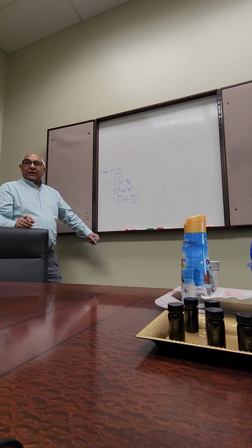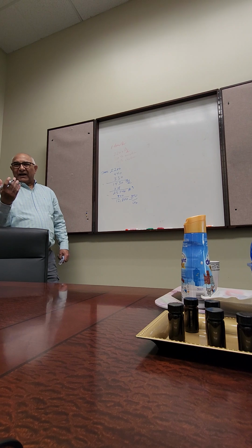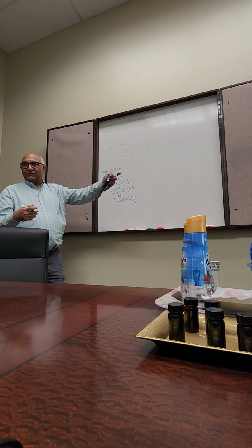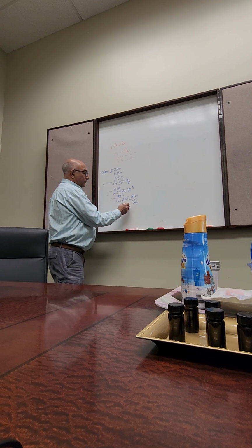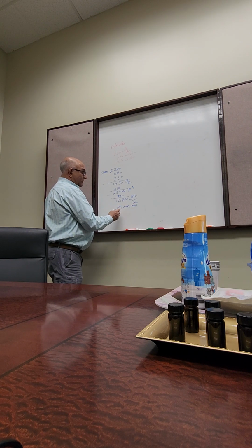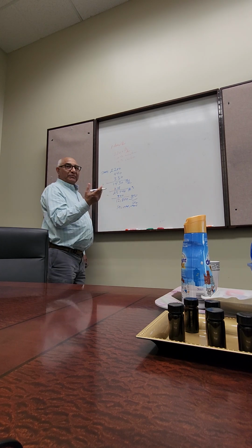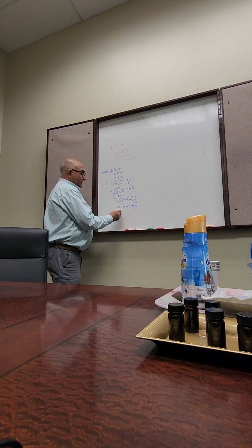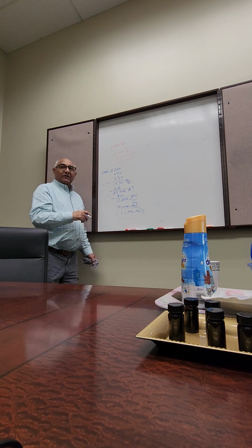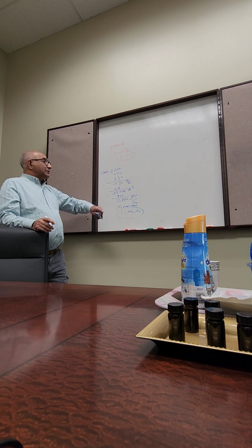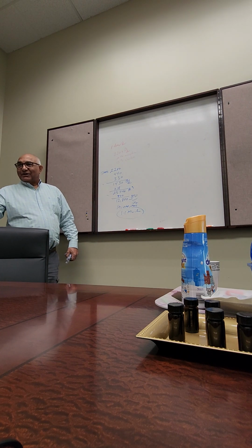Per hour. And from this 12,800,000, I use about 2.5 for operation, for heating and all this stuff. I end up with approximately 10 million BTU. And if you use a generator, normal generators are about maybe 35%, at least 35% efficient. So you get about 1.1 megawatt hour of electricity from a ton of garbage. Okay? So now, if this is cheap and you don't want to do electricity, you have other choices.